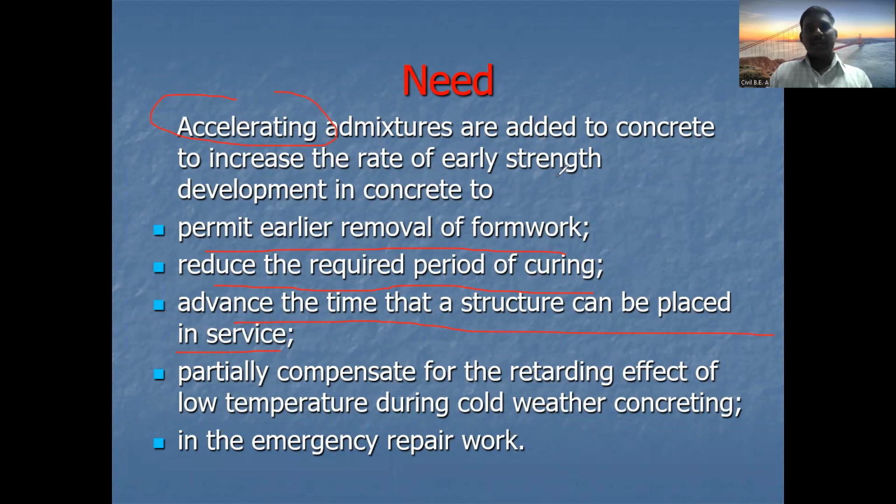At that time, in whatever concreting we are doing, we have to add the accelerating admixtures, and then we will gain strength in early days and can use the existing component or structure in service in early days. For that purpose again we are adding accelerating admixtures, to get the early strength.